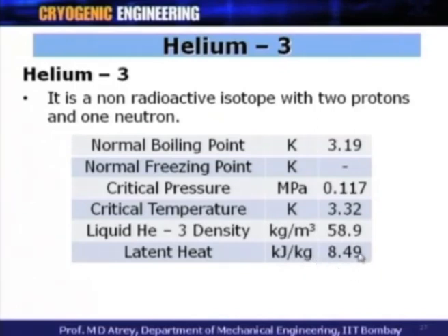It means that with the smallest little heat coming in, liquid helium 3 will get vaporized. So, one has to be very sure about the heat inleaks in this case. Whenever we are using liquid helium 3, the heat leaks have to be really taken care of. There should be no heat leak to the system. Otherwise, liquid helium 3 will get immediately evaporated.